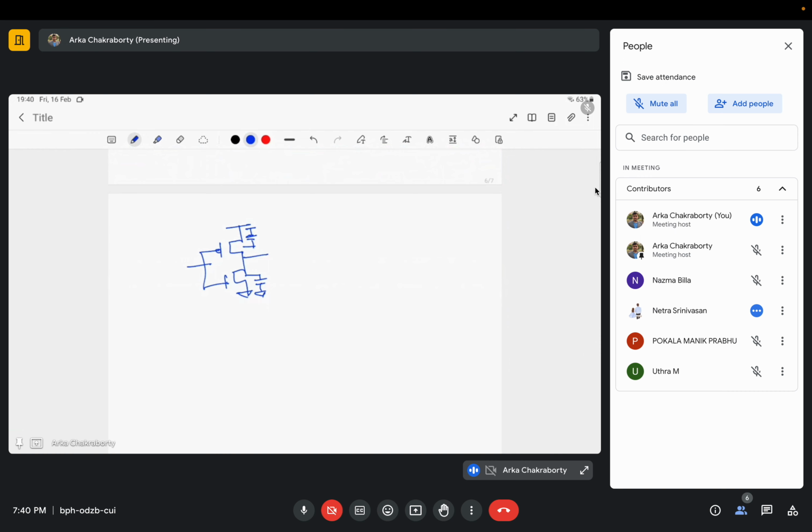Okay, see, it is like, first of all, do you know about body effect? I think I mentioned in one of the classes a little bit. See what happens, this body terminal, generally if we apply some voltage here, the VT of my transistor shifts, the VT of the transistor changes. So in order to remove this body effect, this body is generally connected with the ground, and here this body is generally connected with VDD, so that my VBS